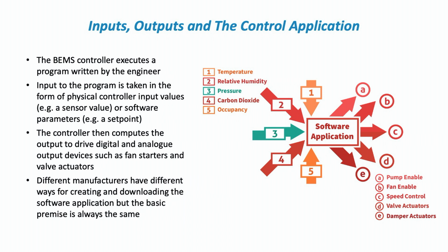This is the mainstay of any computer program. If you are operating a computer program on your desktop computer, it receives input, typically from your keyboard. It processes that input and it provides you with output. So if you're using Word, you press the W key, then the word processor sees the W key is pressed, and it looks at what font you're using, what size that font is, and it displays it on the screen. So that's a software application. Ours is no different. We look at the temperature, we probably compare it against a set point, and we perform a control action based on that. And that is all DDC controllers are doing.